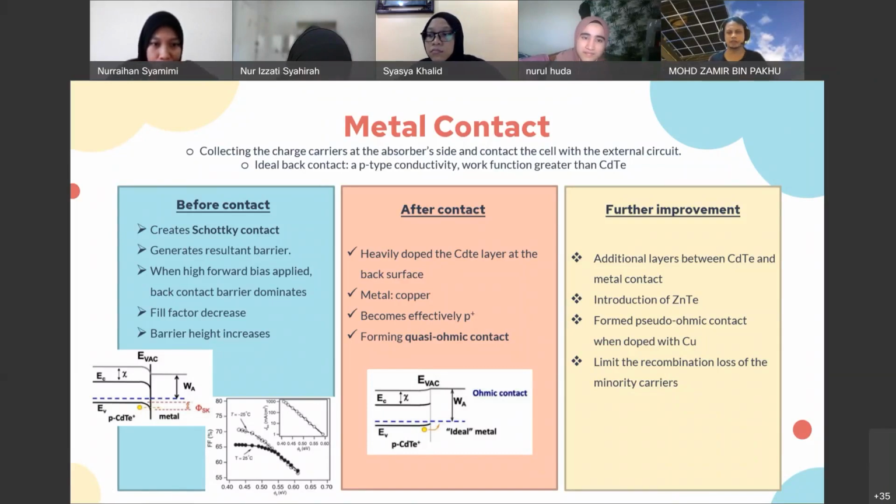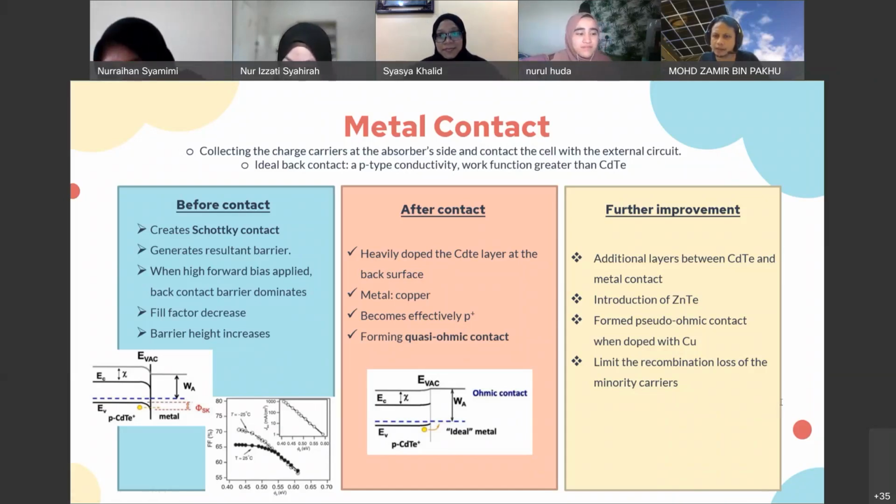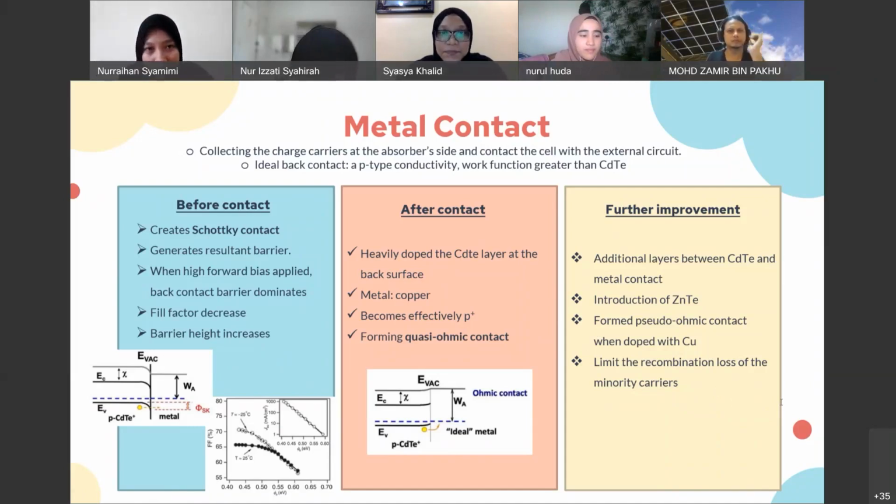So next question. Right, Hasnain, for the working principle part, cadmium telluride is the absorber and cadmium sulfide is the window layer. The question is, can cadmium sulfide be an absorber as well in thin film solar cells? Cadmium sulfide can be an absorber in thin films, but before the deposition, an electron transporting layer should be on a substrate first.